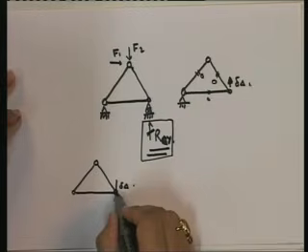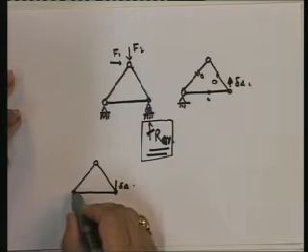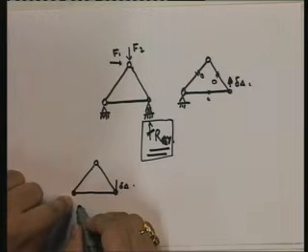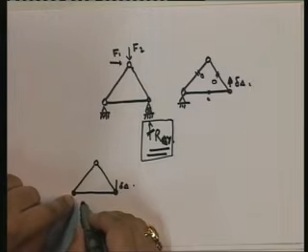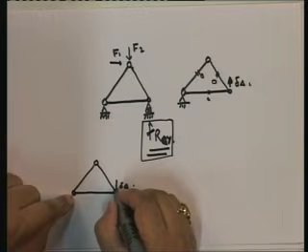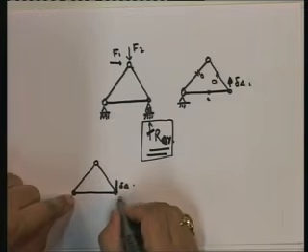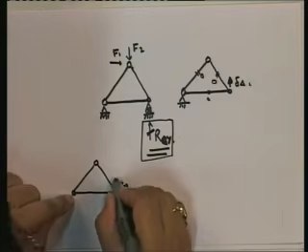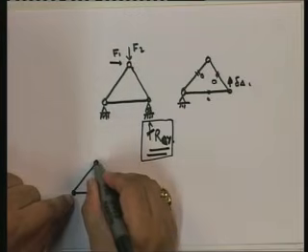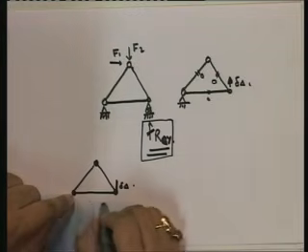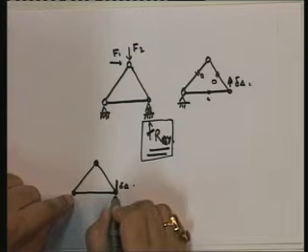Now, will this move in this direction? See, note that this joint is here. Okay, this point cannot go anywhere. And I need to move this way. It does not mean that it only moves in this direction. You have to ensure that every point moves the way it does in a rigid body.